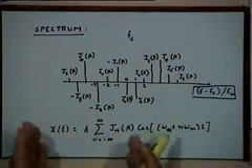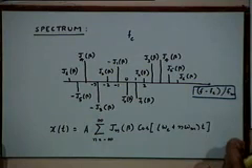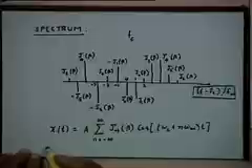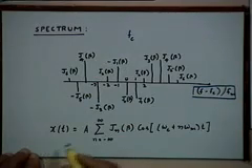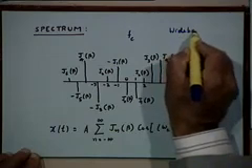So you see a very large number of spectral components present, right. It's a wideband signal. So in general, when beta is not small, we call it wideband angle modulation. So this becomes wideband angle modulation.